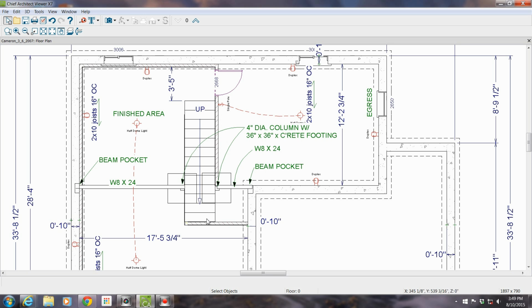So you've got your stairs going up, as I said. Gonna come around here, all foundation wall. Got an egress window. Egress window is like an escape window. It's lower to the floor, the ledge of it, so you can get in it, and then it's big enough so you can get your body through there and then get out of the window well to get out of the basement in case of emergency.